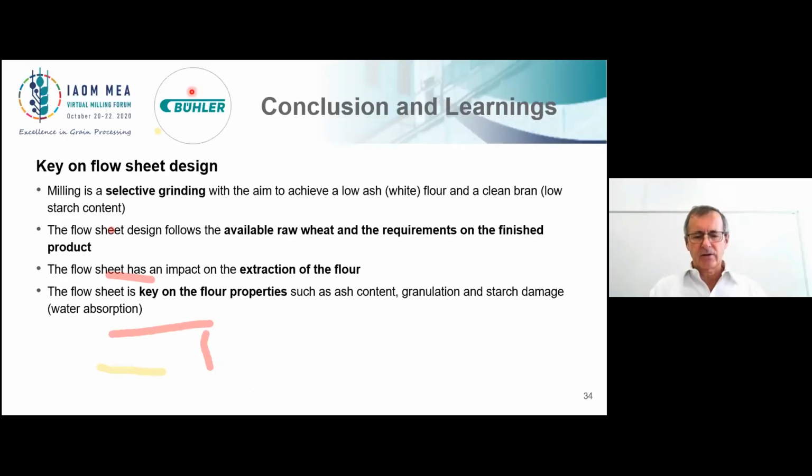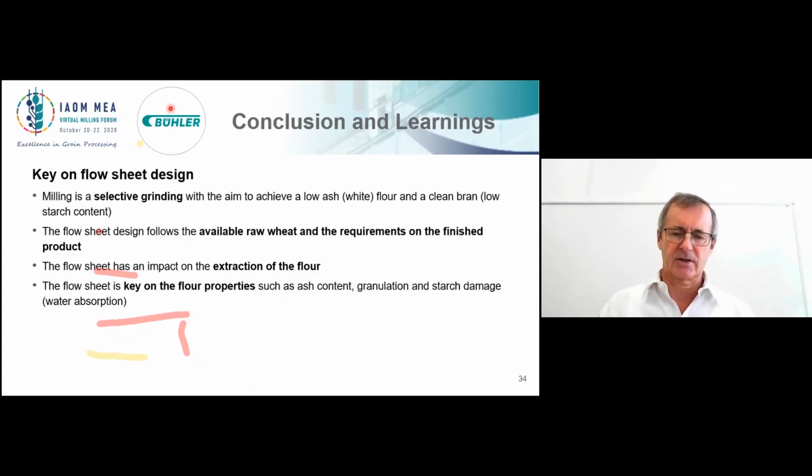But on the other side, the rolls, C1, C2 make starch damage. All the rest is only cosmetic. So we need to work well on the first two reduction rolls. They need to be well tapered, having a good surface, not too smooth, not too shiny, and you will reach an excellent starch damage.